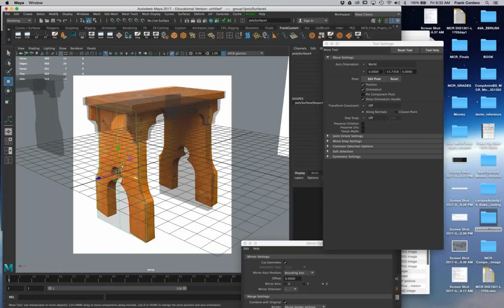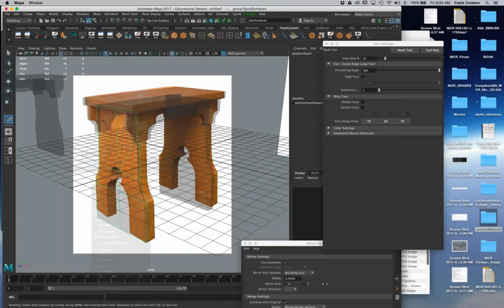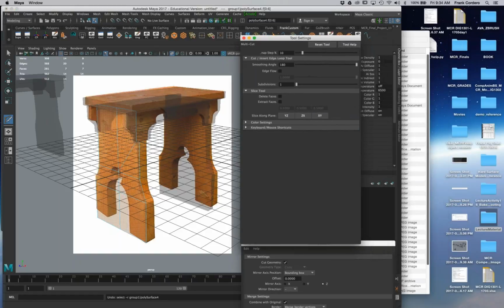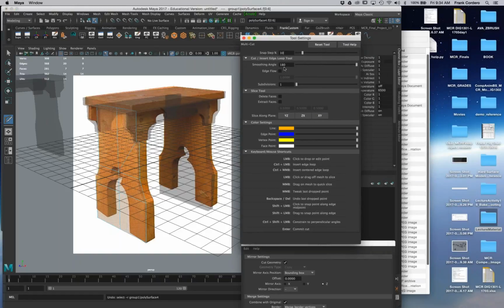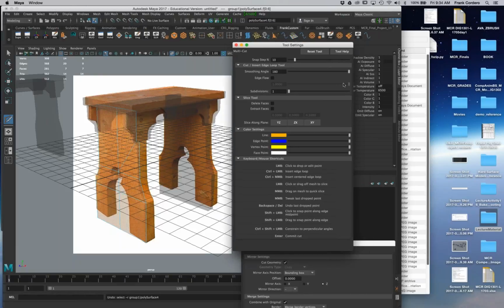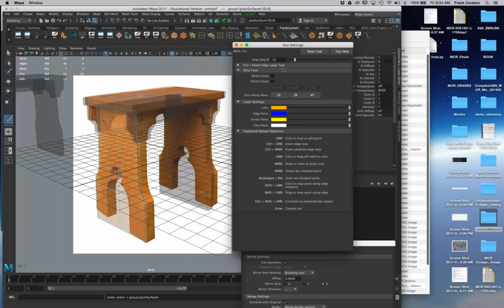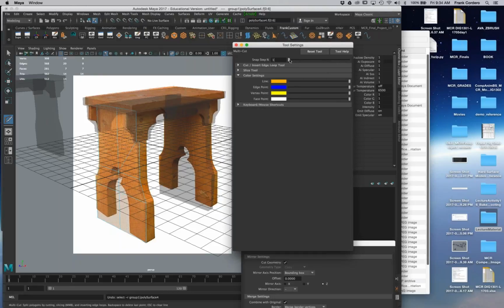What I'm going to do instead, guys, is commit to making the shape I know is there by using the multi-cut tool first. Let's go here. And there's a snapping thing that's going on right now, and that's the hard part. Let me go back. My multi-cut tool has a snapping thing going on here. Let me just see what's up. Step snap. Let me just turn that off.